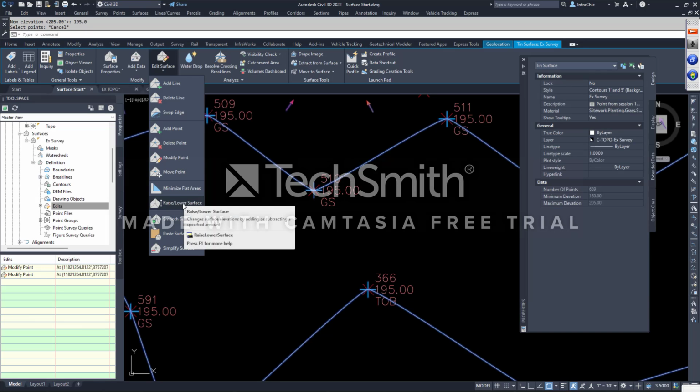You can raise and lower an entire surface one time. Do not do it multiple times. It only looks at the last time you raised or lowered. It will drive you nuts. If you raise it a half a foot, lower it 2.5 and bring it back up 0.3, it won't do any of it. It'll do the very last one. And it will drive you nuts. Literally drive you nuts. Raising raises the entire surface.